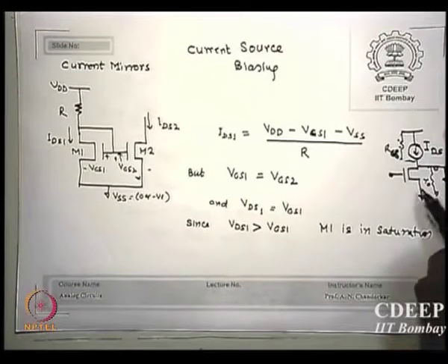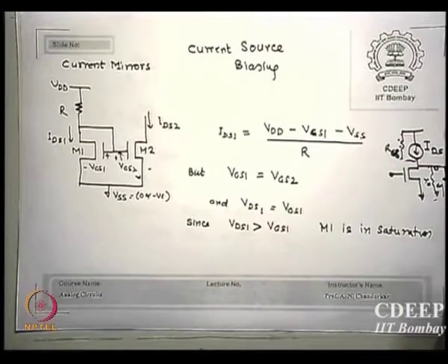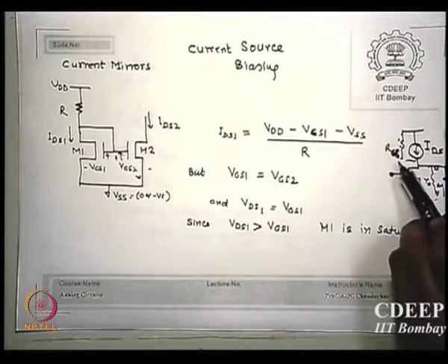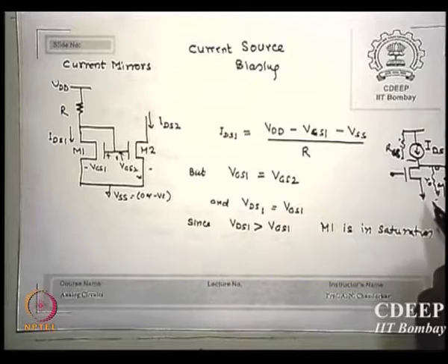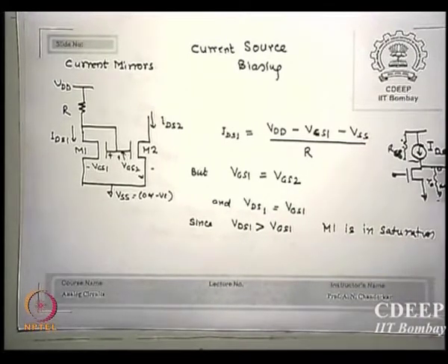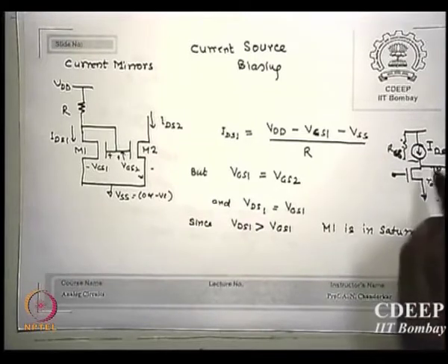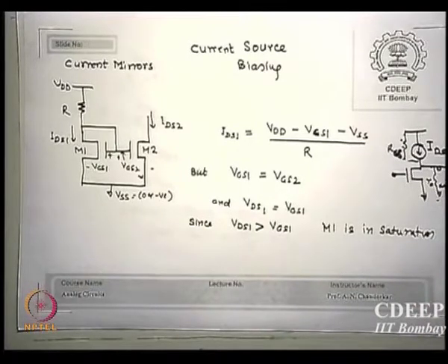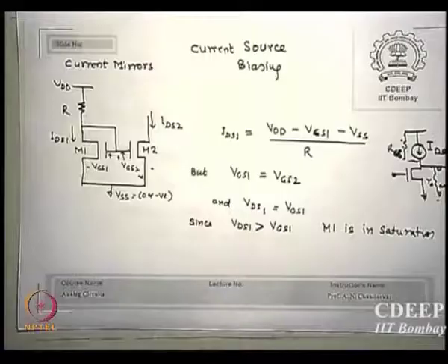Output resistance of the amplifier I want very high, let us say, but this may shunt. So this value should be higher than R0, or at least R0 by 2, then I will get it. Is that correct? So the current source which I am going to use should have higher parallel resistance of itself, as a Norton's equivalent, is that correct? Now how do I get this is one of the methods which I am suggesting to you. Is that clear to you?